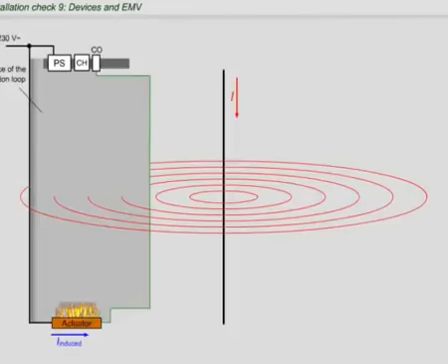At the end, there are still some basic requirements left which are often ignored. It must be checked, for example, if the cables are installed so that the creation of induction loops can be prevented and bus devices are not damaged.